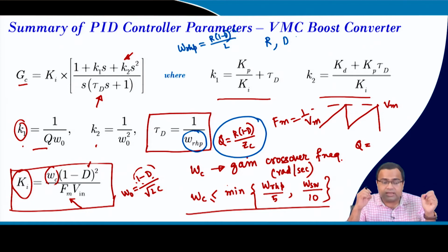If we design by the traditional way, where we design this compensator, the PID controller or type 3 compensator, at the very beginning stage, using off the chip components, and then we leave it, then throughout the process, when there is a load variation or supply variation, we are not going to change it in traditional analog control. As a result, you have to design this controller based on the worst case.